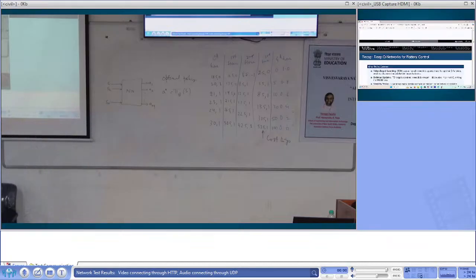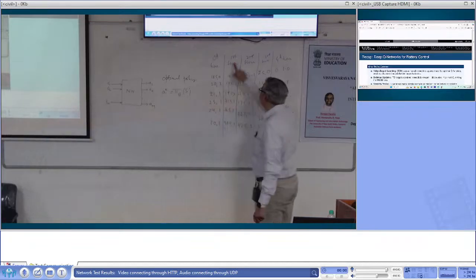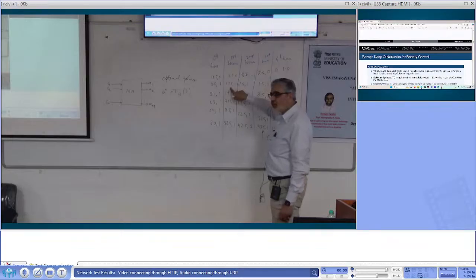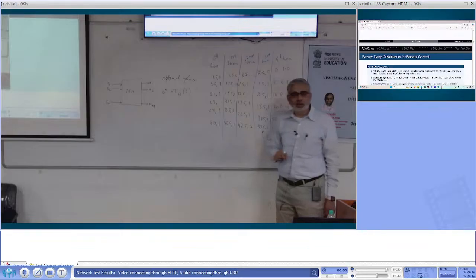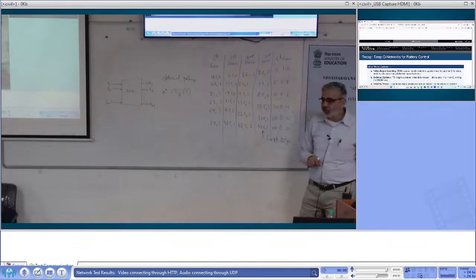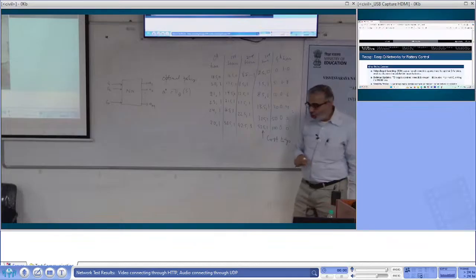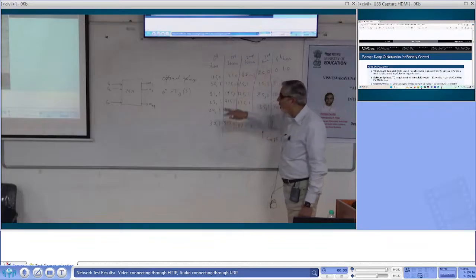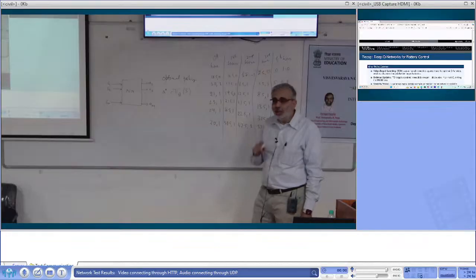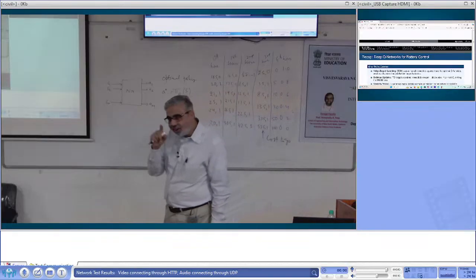Does that make sense? Simple? So we have got a neural network where I put in state and it tells me what is the optimal action I should take. So if I put in the state here, the state 17.5 SOC, first hour, it should immediately spit out -1. You go and discharge. So this tabular information can be captured in a neural network and then we can train it.